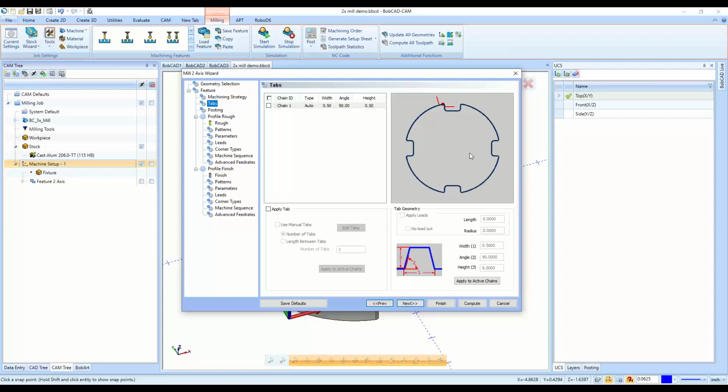And if we don't have what's called a vacuum table, a vacuum to hold the parts in after we've done the full profile of the parts out of a piece of plywood or a piece of OSB, a 4-foot by 8-foot sheet, or any dimensions there. If we can't hold it in with a vacuum, the cutter can go around while it's cutting, and then, for example, at this location, it'll retract. It'll go around this corner and then plunge back down, creating tabs along the corners, and I can add more if I want to here.